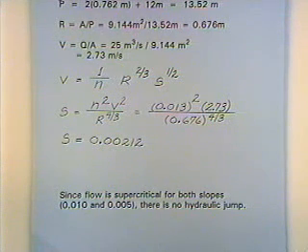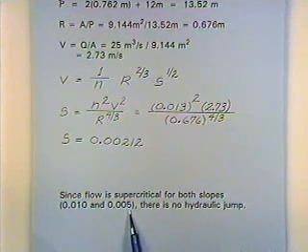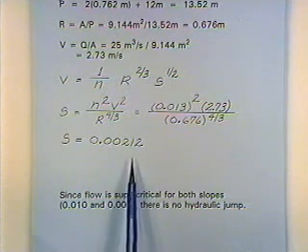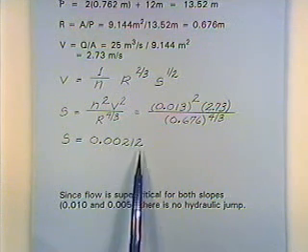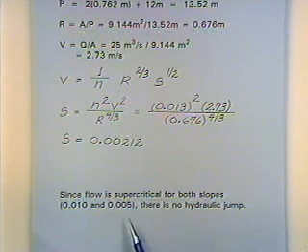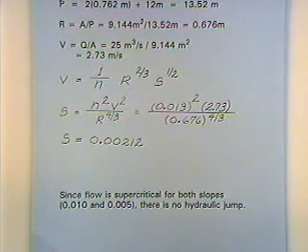So when I come downstream, for the jump to occur, I've got to have subcritical flow, and that's a very flat, tranquil flow, and low velocity means flat slope, and I've got a slope of 0.005, which is greater than this slope of 0.00212 at which critical flow occurs, so I've got supercritical flow. So I've got supercritical flow in both cases. And so if you've got supercritical flow going into supercritical flow, there's no jump. You've got a smooth transition.